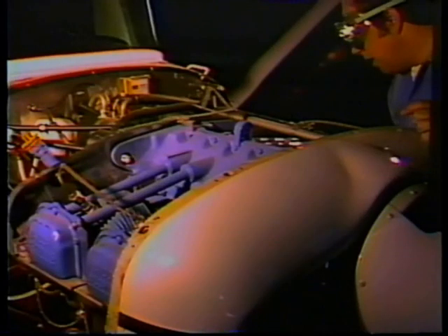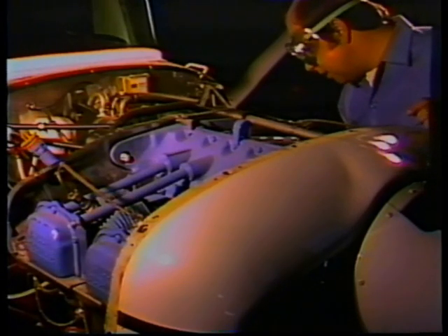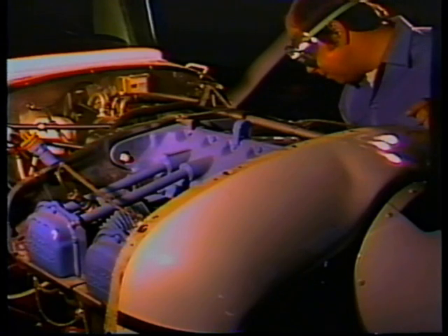If the air valve is equipped with a valve core, release any air pressure that may be trapped between the valve core and the valve seat by depressing the valve core. Under no circumstances should you depress the valve core with your finger or fingernail. When performing this task, always wear protective goggles and keep your face to one side of the air valve, since high-pressure air can cause serious injury.